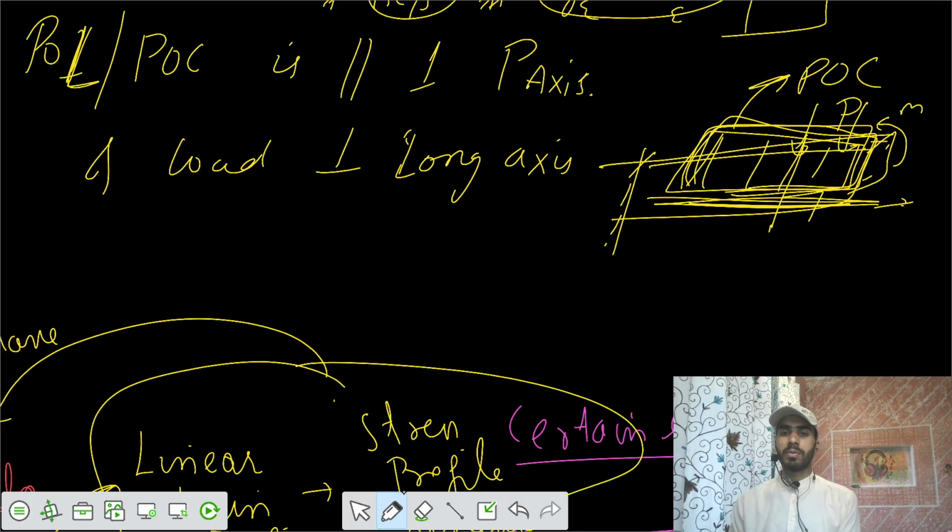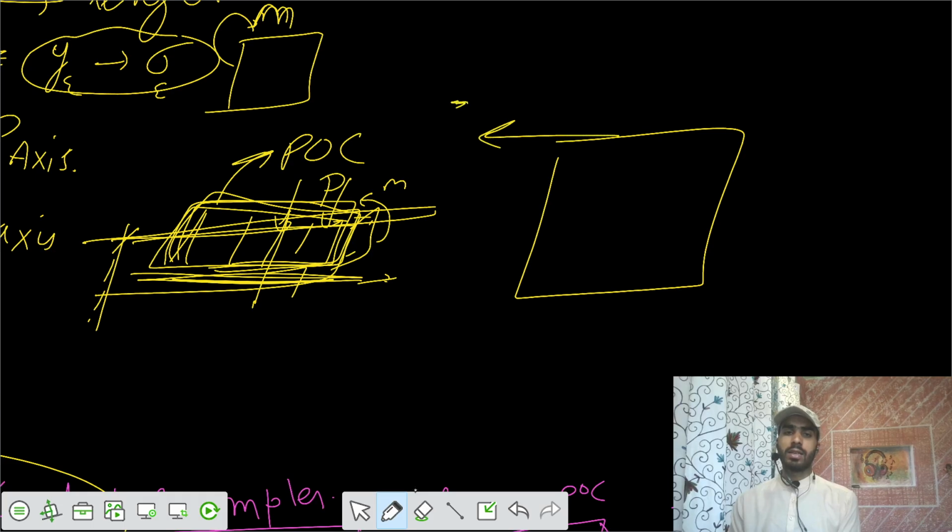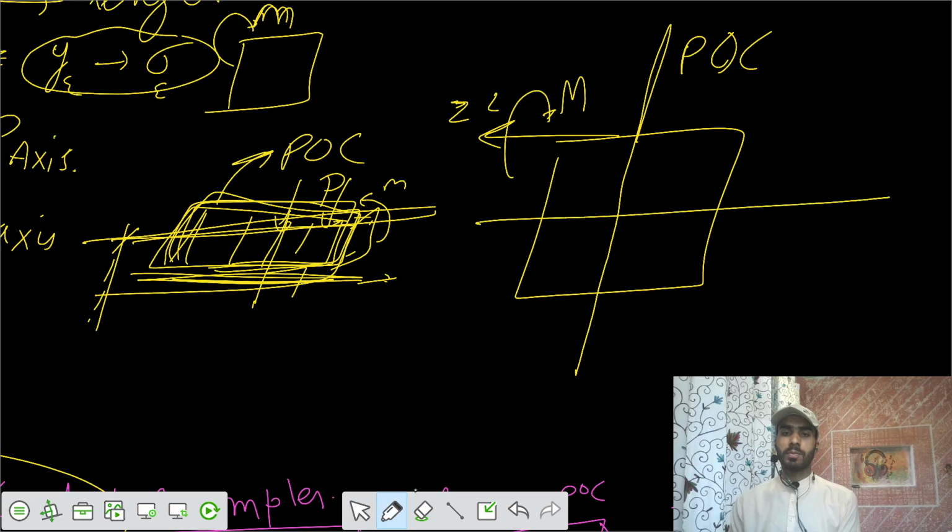One of the principal axes is along the long axis, because from the section you have this z direction, and you're applying moment Mz. So perpendicular to that is the plane of couple. So the plane of couple is perpendicular to one of the principal axes, principal axis 2.